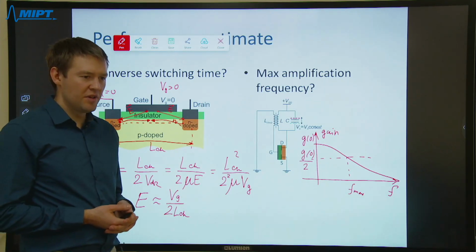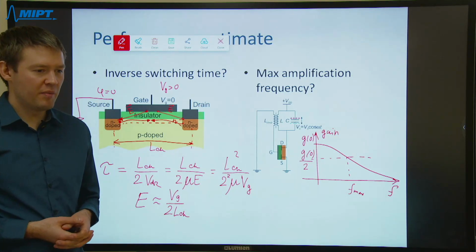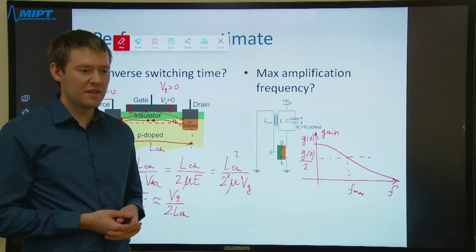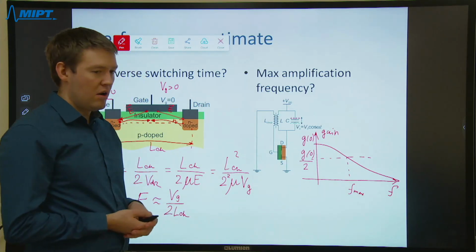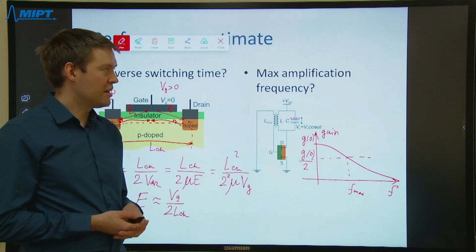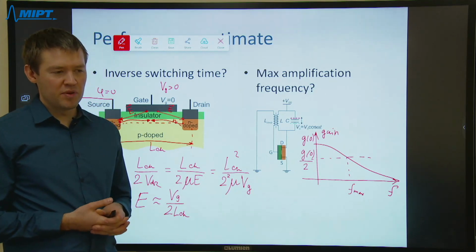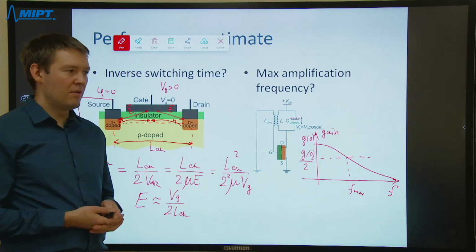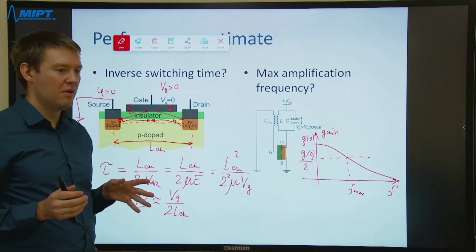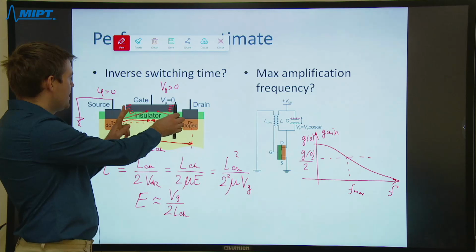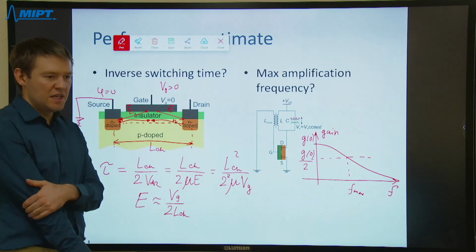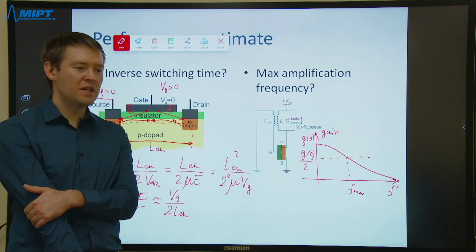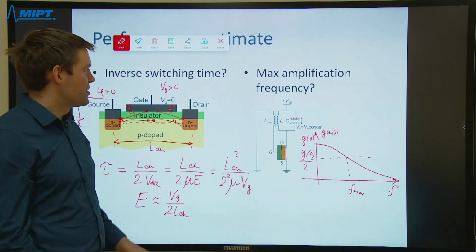And it is actually the driver for shrinking of the microelectronic devices. The smaller is the size, the shorter is the switching time. And this explains the observed correlation between performance and size. This is the reason why now in electronics, and still now, the size of the gate and of the channel is shrunk and shrunk further, and now it reaches, well, roughly 10 of nanometers in contemporary processors.